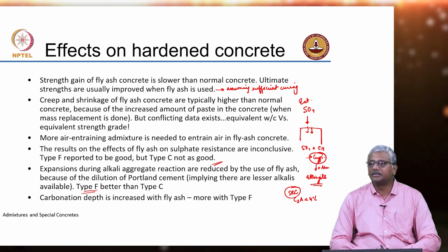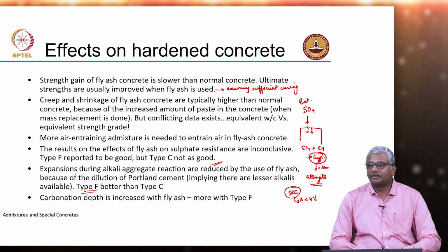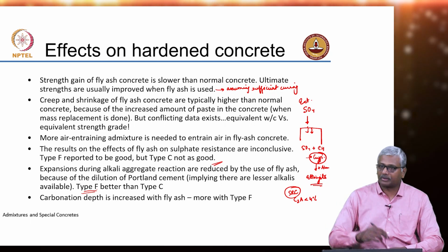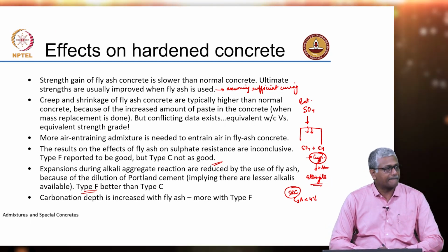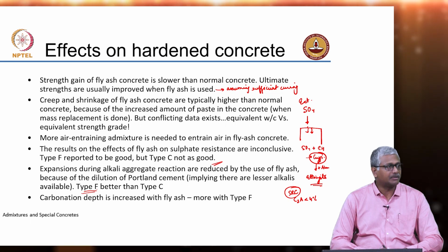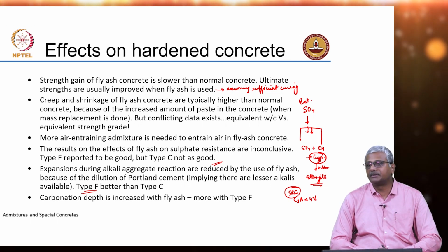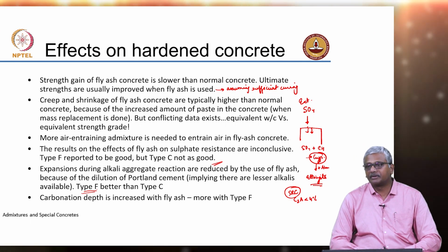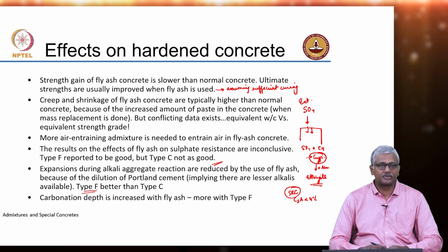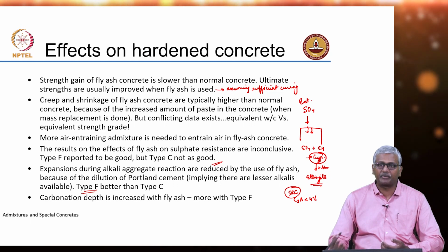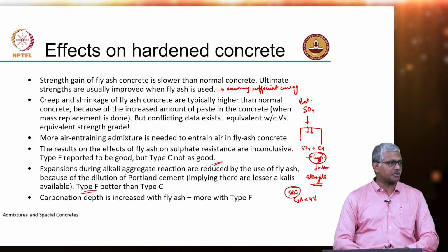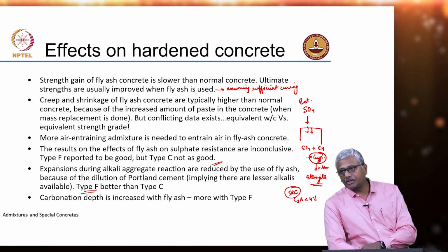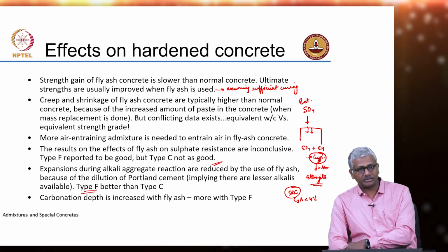What is carbonation? Attack of concrete by atmospheric carbon dioxide. So, carbon dioxide penetrates the concrete. What is it going to do first? Again, the first reaction will be with calcium hydroxide, and what will that produce? Calcium carbonate, right. That is your lime mortar reaction. No? Atmospheric carbon dioxide reacts with calcium hydroxide to produce calcium carbonate, that leads to hardening of a lime mortar. Your strength gain of lime mortar is basically this carbonation reaction.